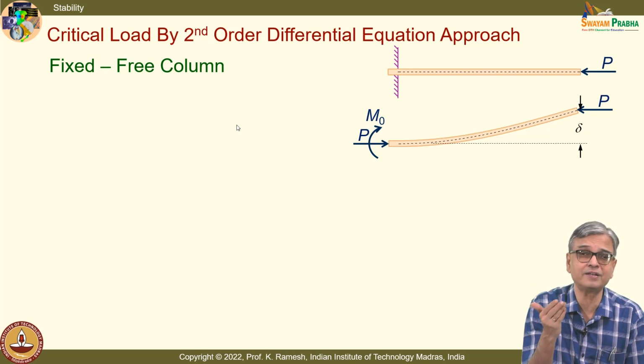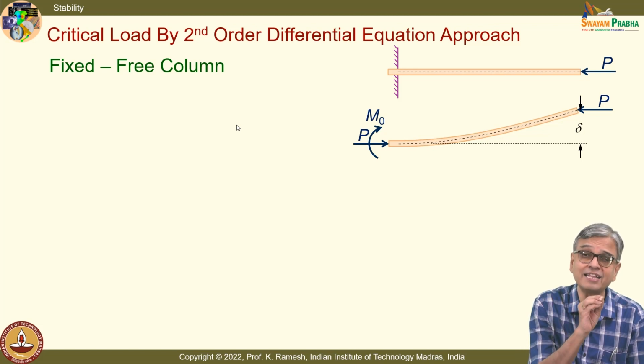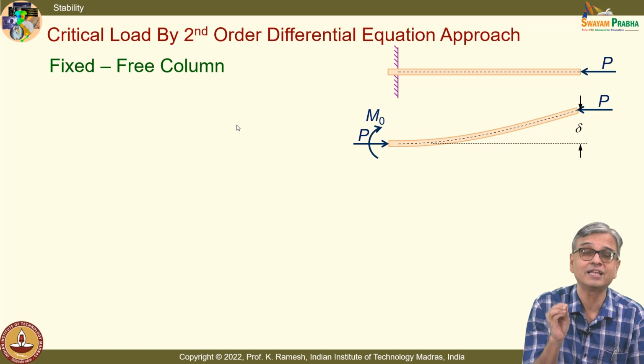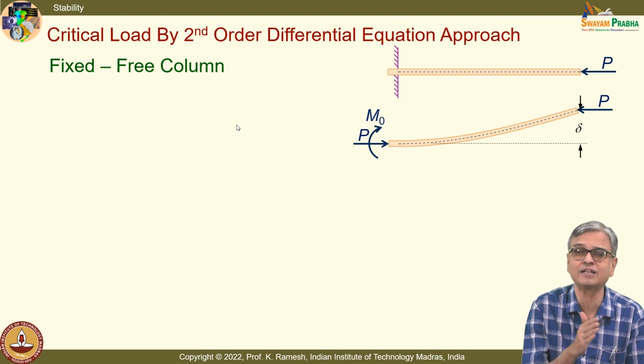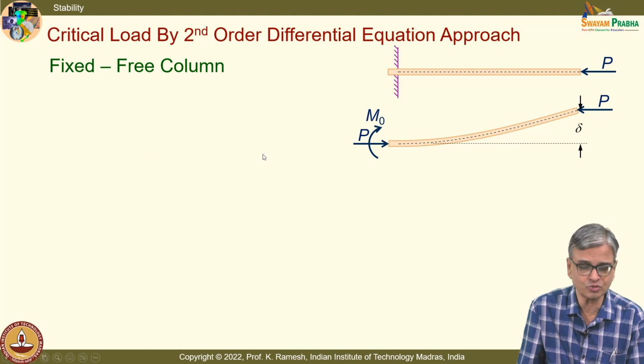While we developed deflection equations, we also developed d power 4 v by dx power 4. We said that equation is useful even for statically indeterminate problems. So, that is why you find that equation is used for developing the critical load, because except the fixed free, all other situations are statically indeterminate. But there is also a school of thought that people directly use the second order differential equation approach.